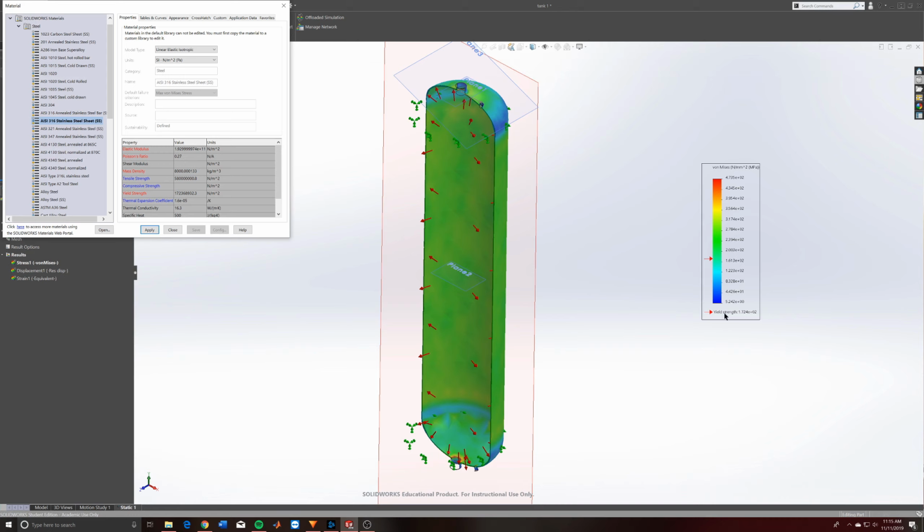Now, when you do something like this, make sure to mention that you are comparing it to the ultimate tensile strength and not the yield strength. But also always mention where it is yielding in the material, and a quick blurb as to why, or what's going on, and why we're going with the ultimate tensile strength instead of yield stress.